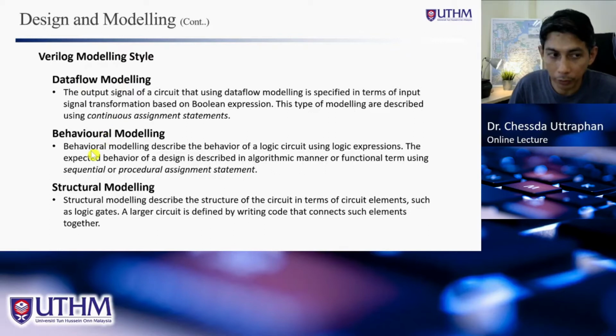All right. But if you use behavioral modeling, you need to describe the Boolean equation inside the always block, because you need to use sequential assignment statements. And if, for example, you don't have a Boolean equation because the specification is a little bit complicated, and of course you don't have the schematic either, then you need to use behavioral modeling, using the behavior of the circuit.